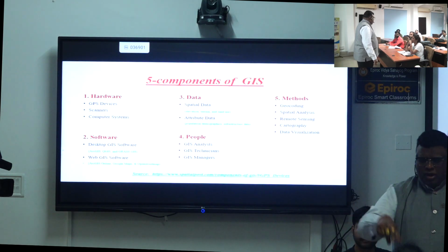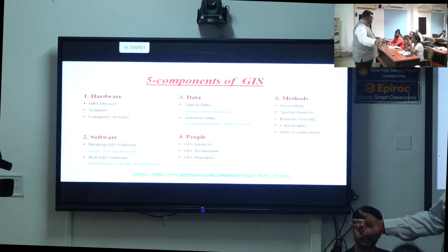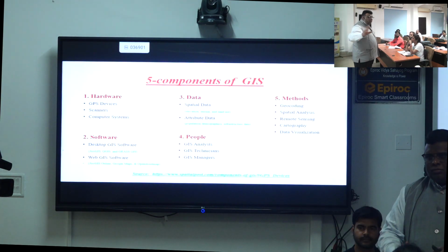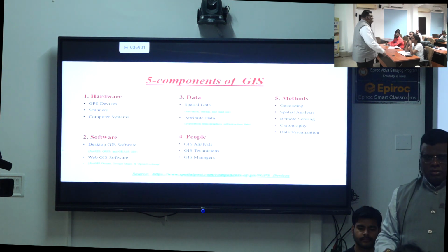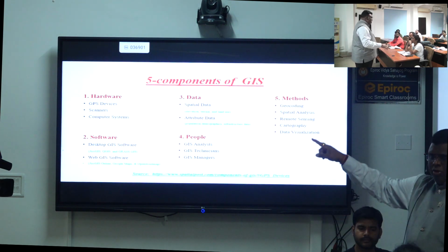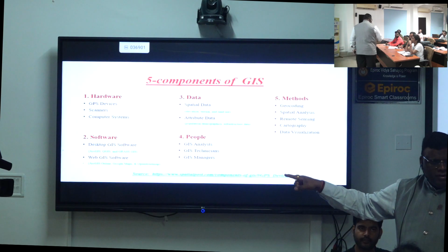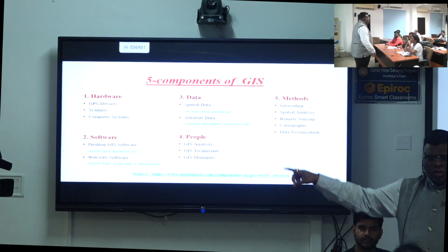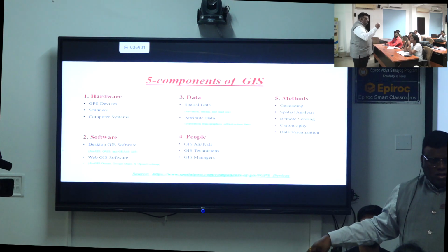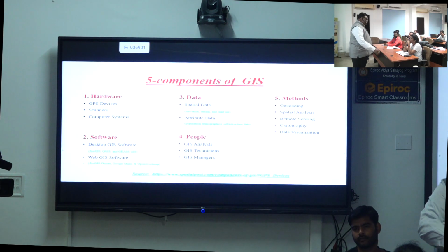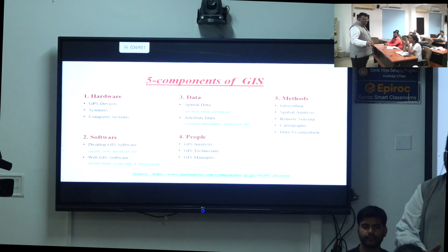But how will I get that? By using the non-spatial or attribute data. These two have a connection. I think in the lab you might have seen, if you select the components on the map, the attribute table is highlighted. Or if you select some of the features in the attribute table, they will be highlighted in the spatial view, because both have a relation.